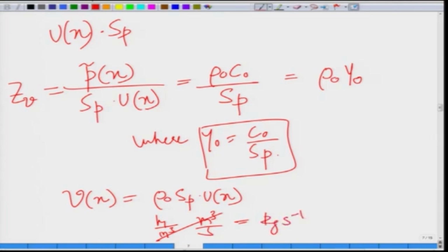The reason that I am introducing this quantity, and as is conventionally used in muffler acoustics, duct acoustics, is that typically the mass flow remains constant. When you multiply by density, density might be at the upstream part, it might be the air is hotter. So, it is a lighter thing. So, density is relatively lower compared to the density at the downstream, but what essentially remains constant. So, the volume velocity might fluctuate, but mass velocity is always constant. So, people do work in terms of mass velocity.